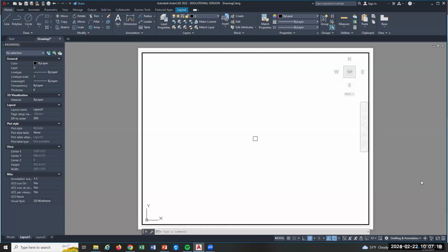So if you're ever wondering, am I really in metric or not? Just go into here, go to your viewport, do it 1-to-1, and it should look tiny on a piece of paper. If it was 5 inches, that would be near half the page, right? A substantial difference.